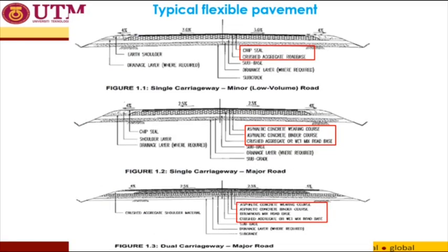So in general, pavements are usually composed of layers of different materials which have a significant impact on its performance. The composition, density and thickness of paving materials such as bituminous materials, stabilized granular materials, unbound granular road base and subbase shall be selected so that they can perform and meet the intended performance requirement.